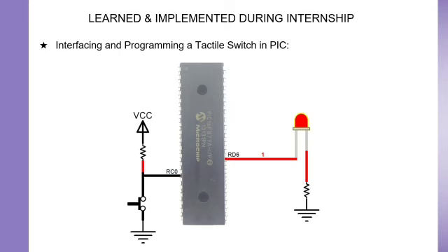Inside the switch, there are moving parts. When you push the switch, it initially makes contact with the other metal part, but just for a brief split of a microsecond. Then it makes contact a little longer, and then again a little longer. In the end, the switch is fully closed. The switch is bouncing between in contact and not in contact.